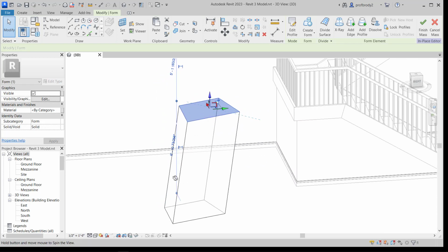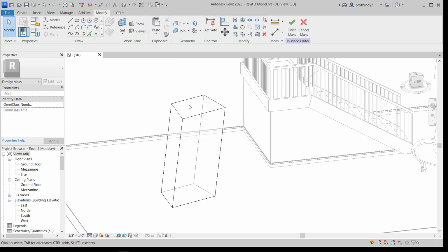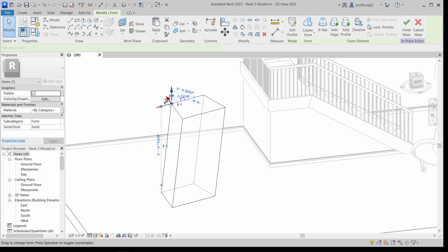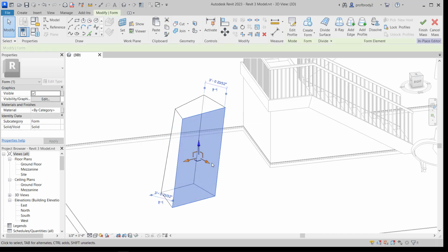SketchUp's axes. But the other funny thing that you can do here that you can't do anywhere else is you can manipulate some of these elements. So for example, I was moving this whole top plane. In Revit, as you mouse over different elements, see how it highlights either the whole surface, this line, or I can even grab a point. And each one, when you click on it, you'll get a different gizmo. Okay. Here, I'll move over this surface. If you're not getting what you want, hit Tab, and you see how it will cycle through the different elements.